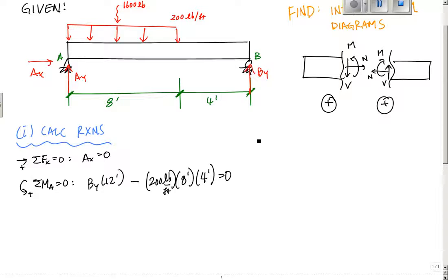Then I use my spiffy calculator, calculate it out, and that number is 533.33 pounds of force. LBF is pounds force. In mechanics, usually you deal with pounds force. It's not like fluids or chemistry where you have to deal with pounds force and pounds mass. Here in mechanics and statics, all the pounds that you're going to deal with are pounds force.